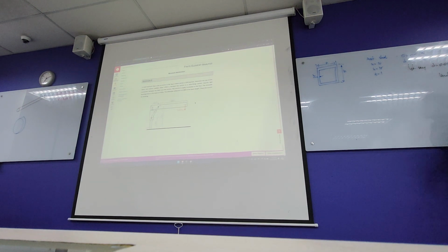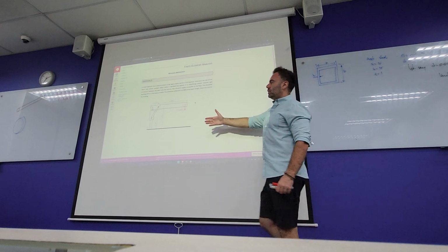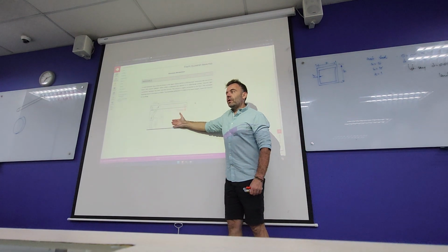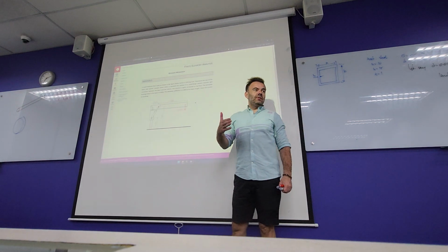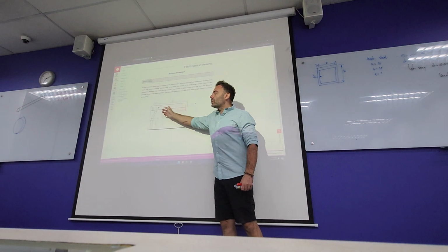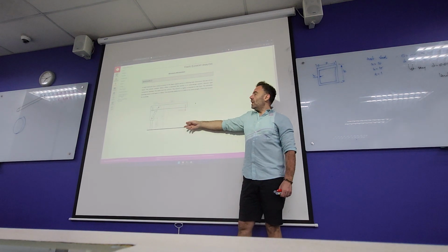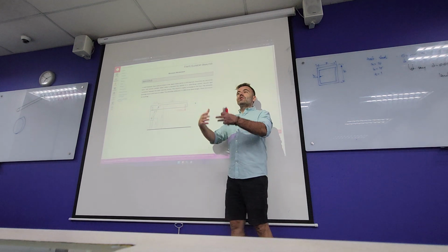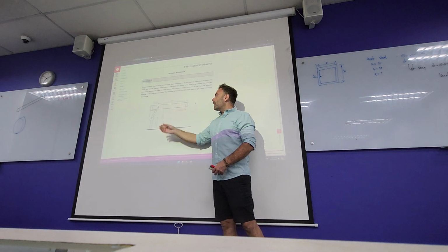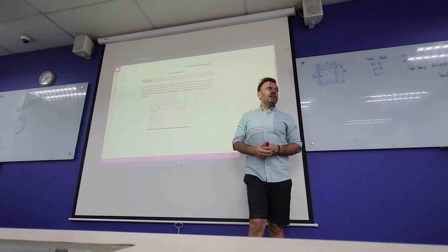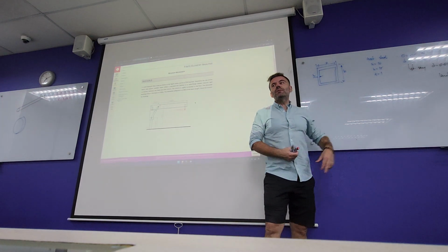The other thing is, you have to be mindful of the role and the purpose of this. It's a crane. A crane is supposed to lift load, safely. But imagine the actual beam is 20 tons and it's only supposed to lift 2 tons. You're going to spend lots of energy, electric power, whatever, just to move the crane around. So think of the context when you're deciding on those parameters.